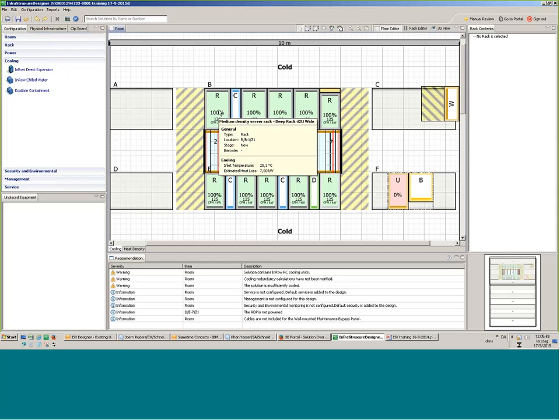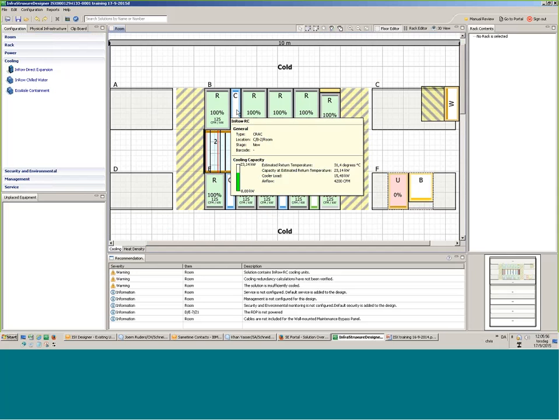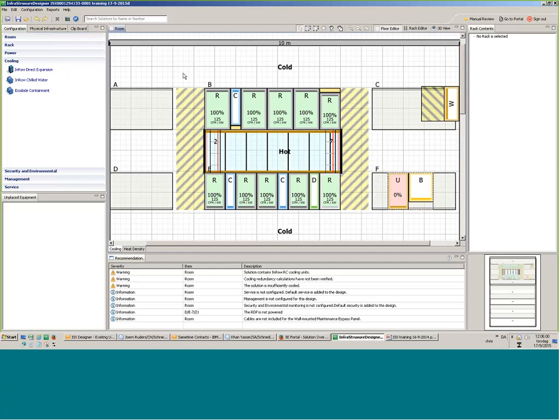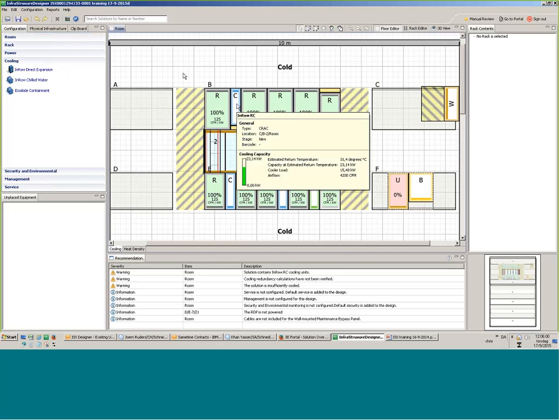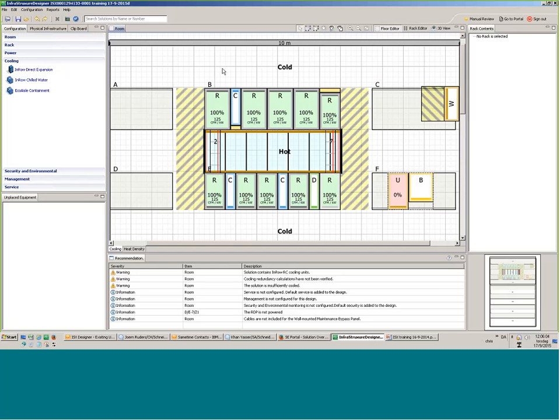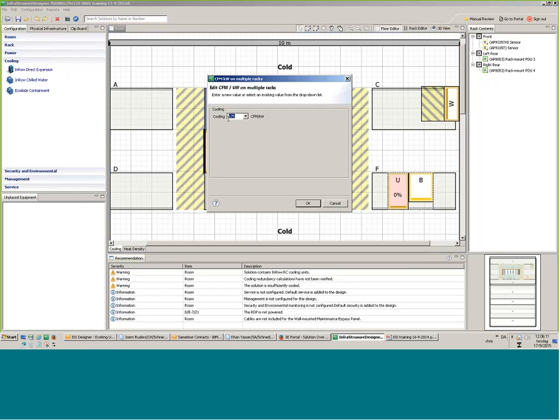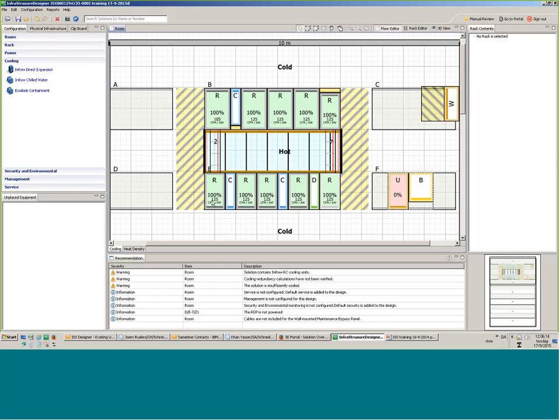So we lose a bit, 10% we normally calculate of loss. So it is plus 0.6, which we calculate here in the cooling unit. Yeah, so that's why we have such difference. If you want to change the CFM and say, hey, I have a blade server, 16.7 delta T, you can do that. It helps us to determine if it's correct, if your cooling unit, if your solution would work with less cooling units.